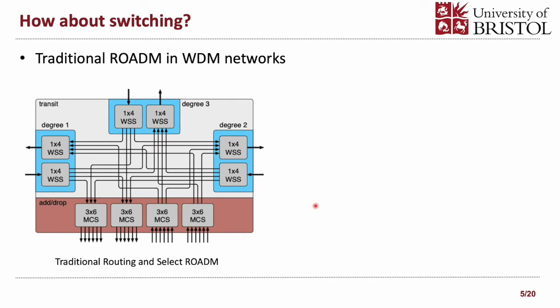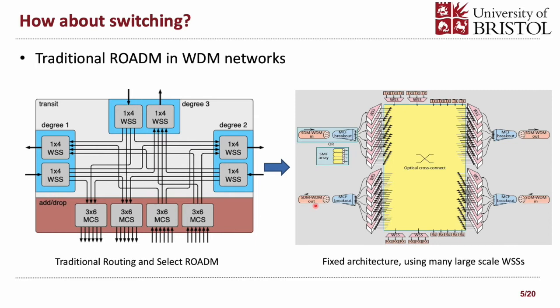If we treat each core as a single mode fiber, the question is, can we scale up this design to support multi-core fiber-based SDM networks? In that case, we will require a multi-core breakout to separate the multi-core fiber into different single mode fibers, and we can do similar things to design the route-and-select ROADM.